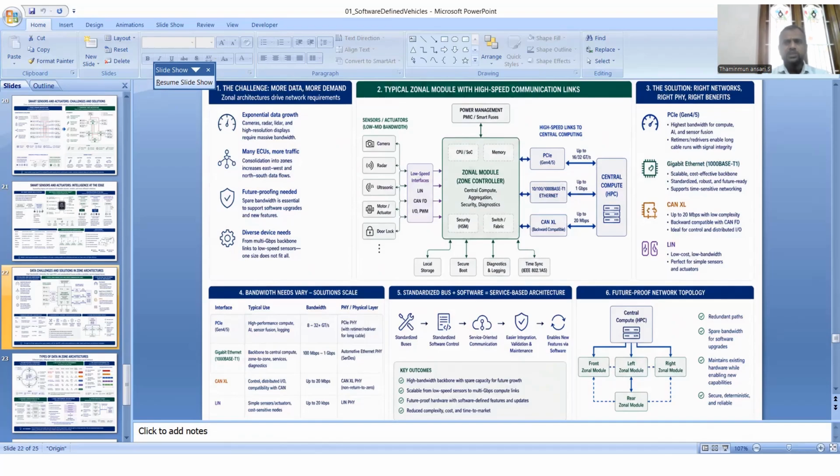Finally, the LIN, which is a low cost version of CAN, which has similar characteristics to CAN. It uses single wire communication, and has been designed by a consortium for a low cost option. It can support a much lower bandwidth. These are the different choices that we can make to address the challenges that we discussed when it comes to data.